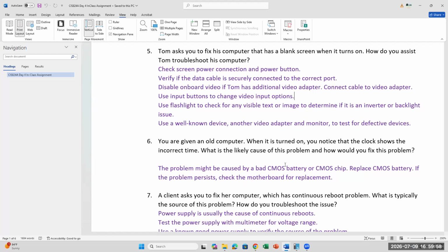So when you have the USB-C port, you can get an adapter. I know Apple integrated USB-C also for display, but make sure you get a cable that's USB-C capable of display, because not all USB-C can do that. Some of them are only made to transfer data or charge or both.